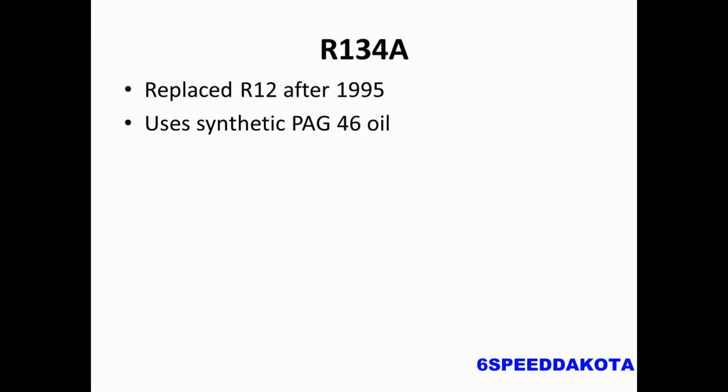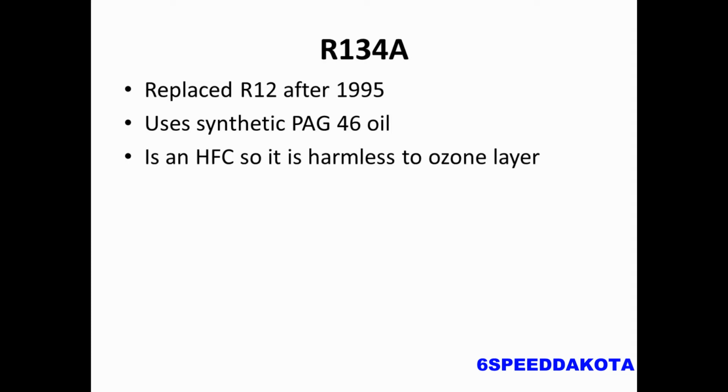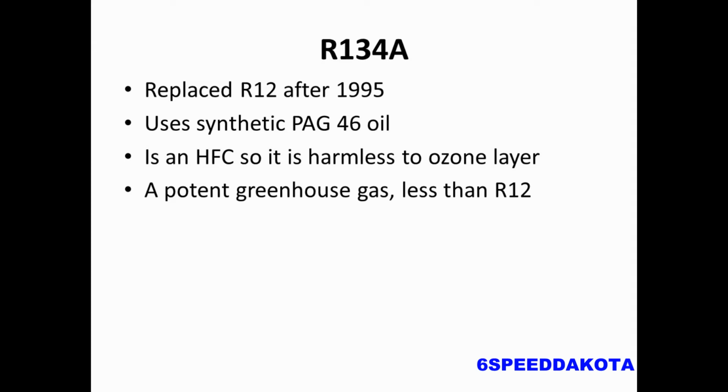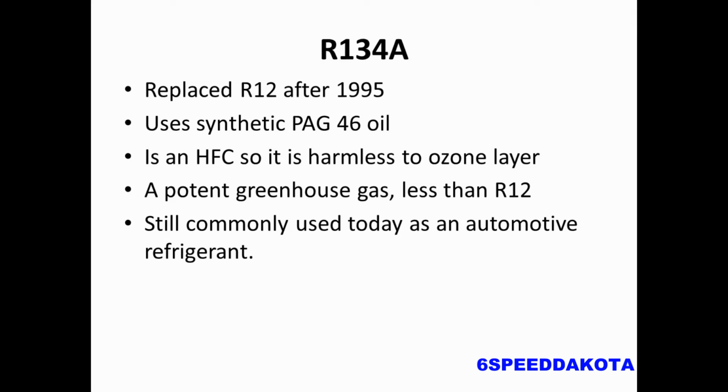So R134A, again, is an extremely common refrigerant nowadays. It's still even used in new cars today. It replaced R12 after 1995 model year, and we use synthetic PAG 46 oils. Again, some hybrid vehicles use something a little bit different. It's what they call an HFC, or a hydrofluorocarbon, so it's actually harmless to the ozone layer. But it is a very potent greenhouse gas, though not nearly as bad as R12. Like I said, it's still commonly used today.